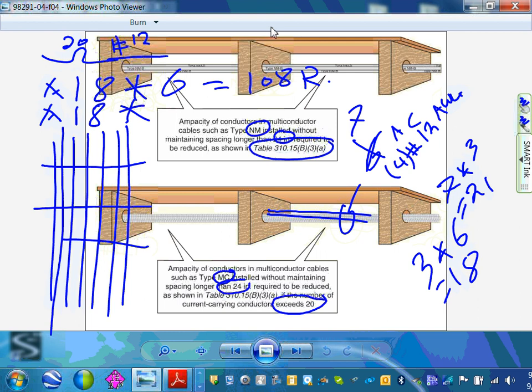If you're doing lights with these 18 circuits, typically what we do, and I'll go over the math, guys, is we put 18 lighting fixtures like this on 1 circuit. Multiply this by 18. What would that give you? 324 lighting fixtures on 18 circuits, 20 amp, number 12. Does that make sense? It's a lot of juice coming out of it.